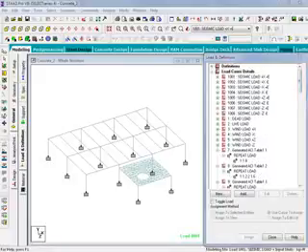In addition to generating our load combinations, we can also use the Load and Definition dialog to create a load envelope. Load envelopes are groups of load cases set under a single moniker. Now for this model, we are preparing to design the beams, columns, and slabs in the Reinforced Concrete Designer within STAAD.Pro, and the load envelopes will be used for the design of concrete beams and slabs. So when doing this type of workflow for your beams and slabs in conjunction with the RC Designer, it's important to create some load envelopes as well.